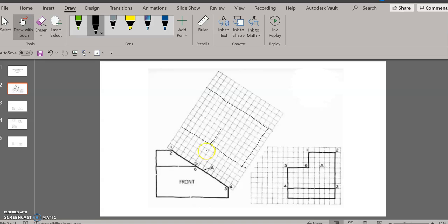Okay? Now the back surface or the top surface goes over 5 from the back, and that's going to be located on this line. And I can connect those two together because I'll have an edge. And that is the auxiliary surface of A that we have. However, I do have the background lines that I have to draw. If I look at this lower corner, that's going to project up onto this line.